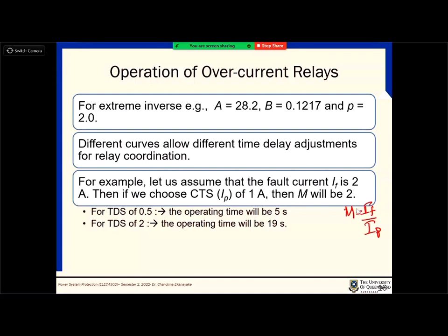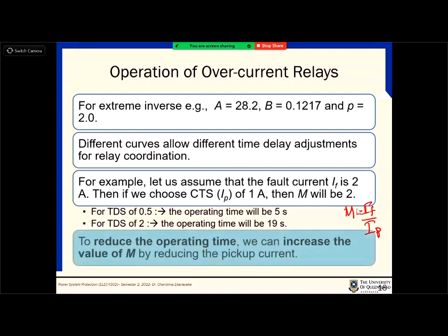But sometimes we are not capable of achieving that fast operation in relay coordination, because certain relays have to act faster, and the other relays have to act slower than the fastest relay, which means you need to take an action based on the operation of the relay in front of you. In that condition, it will be a different TDS value. We'll look at those things.